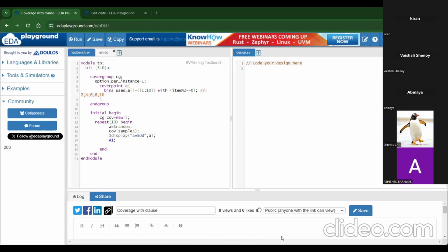Basically, we have a cover group that will be instantiated in our coverage model or the coverage collector. So this cover group, again, we need to sample it, right? That's what it's saying. The cover group samples transaction data that has been extracted by the monitor from the interfaces tied to the DUT pins or bound to the internal DUT modules, which I have explained initially. That is what they are mentioning.